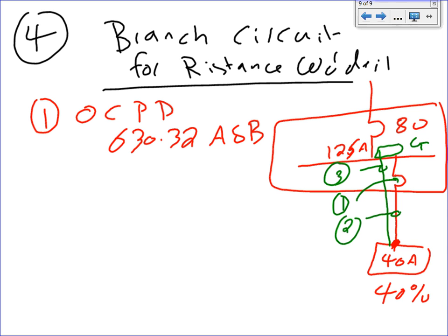Now, if I decided to move it up because I don't want to put two of them, you still have to put one at the top because of the conductors. But I'm going to do it at the top anyway. If the supply conductors of the welder are protected by an overcurrent protection device set at not more than 200%, then you do not need a 300% here. With this, I'm going to size based on 200%, and that will save me putting two overcurrent protection devices, one here and one here. What would be the point?